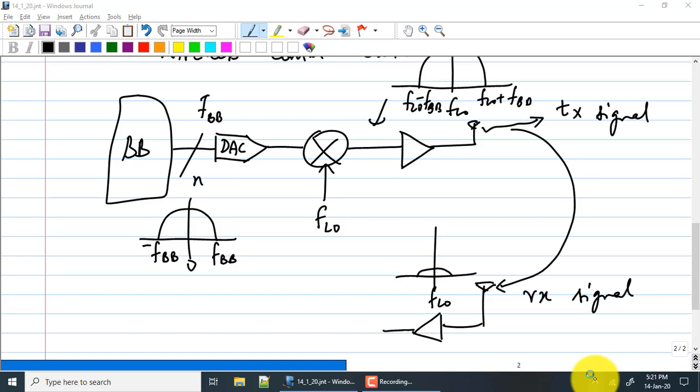Having said that, obviously a lot of these frequencies are close to the frequency where water absorption of energy is very high. Your microwave oven, for example, works at 2.4 gigahertz. That happens to be very close to the frequency where water absorption of energy is as high as possible. That's why you use that for the microwave oven. A lot of your cellular frequencies are close to that. So you could indeed have local heating of tissue. In this case, the power is not as high as in a microwave oven, but in the microwave oven you are heating something for a few seconds or a couple of minutes.